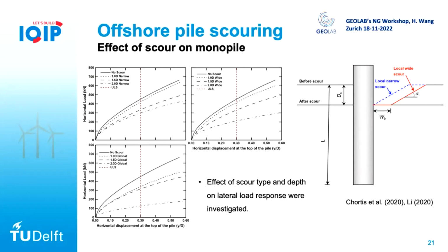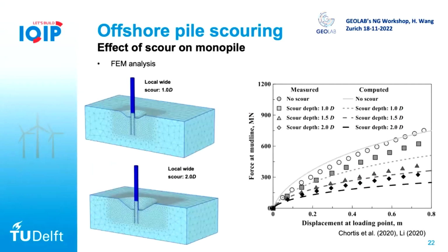And apart from that, we also did finite element simulations. We also performed the numerical simulation to back-analyze the centrifuge test results, and use our validated numerical model to do more parametric studies. Using the finite element model, we can also look into what's happening in the soil-pile interaction, like the p-y curves. So this is also something ongoing in our project.